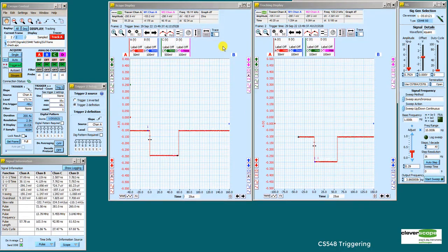Right, I've gone back to the square wave display that we had before and got rid of the digital so we don't have to worry about them. Now we've got this waveform that we can change the duty cycle on. If we add some of that other waveform like this, we can see that the two pulses are not aligned with each other. The question is, can we trigger only when the pulses are aligned? Let's do a bit of work on that.